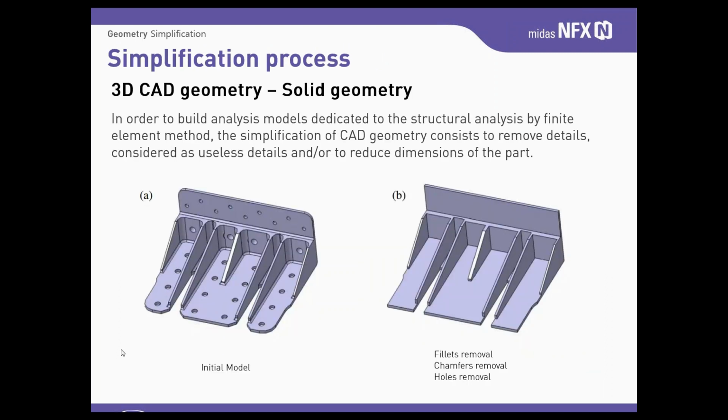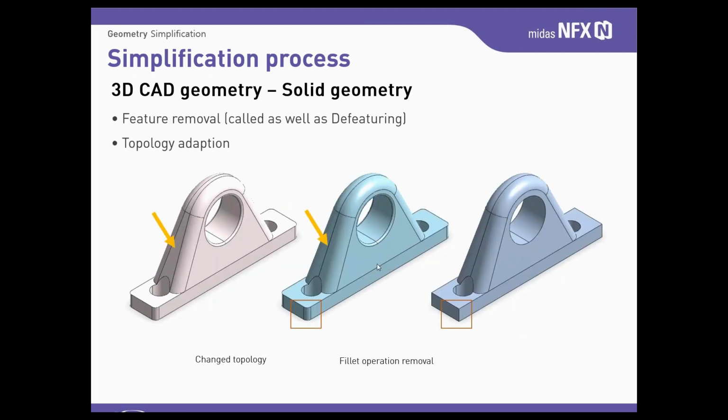So that's the basic law, we can say. Now finally we're touching the simplification process of cut solids. Before the meshing step, simplification is a way to enable robust mesh generation and to obtain directly the shape required for FEA without some local adjustments for a finite element mesh. Simply saying, we have an initial model and, based on our judgment, we are removing unnecessary features or even changing model dimensions. So simplification is not only feature removal, which I will talk about right now.